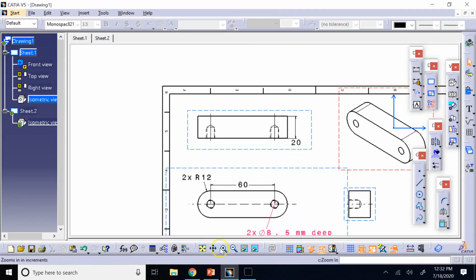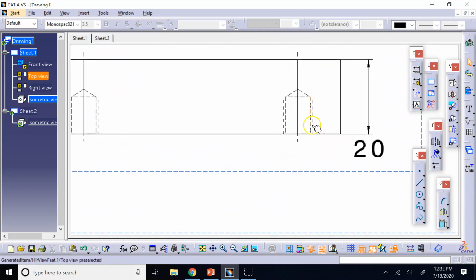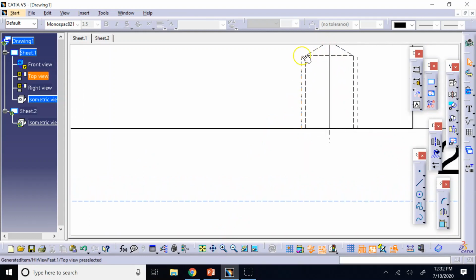Now what has changed? Look. Now there are two lines. The first line, the inner line, is the drill. The second line is for the major diameter of the thread. So these double lines now would tell you this hole is threaded. And they can also tell you how far the thread goes. So here the thread has gone all the way to the end of the hole.